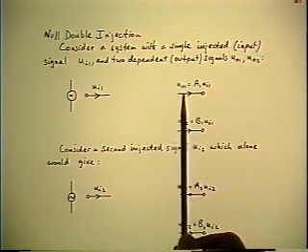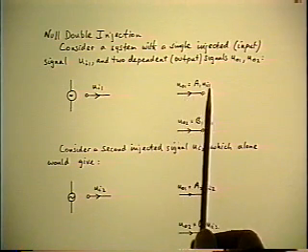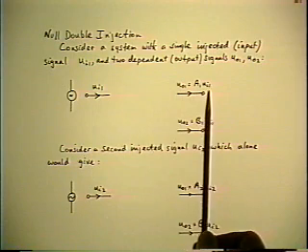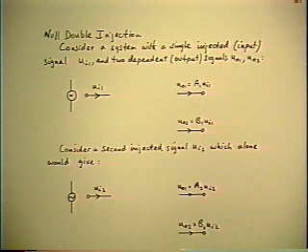So it's a U O1. And the only thing that I can say about it is it's proportional to the independent input, and the proportionality factor is something I'm going to call A1. A1 is a constant if the system is linear. Constant in the sense that it does not depend on the signal amplitude, although of course it may be a function of frequency.